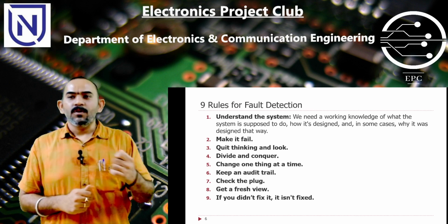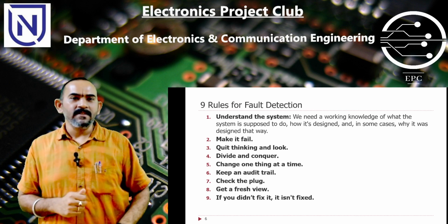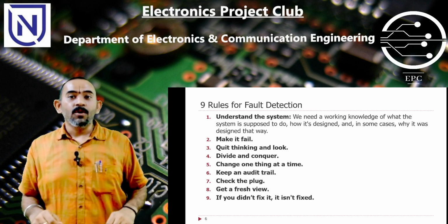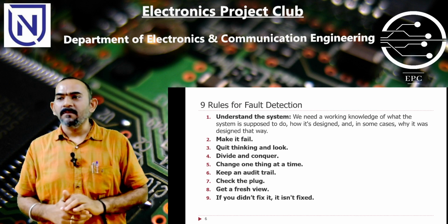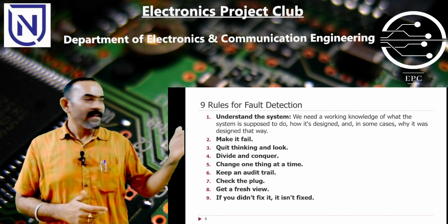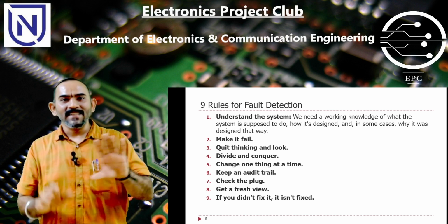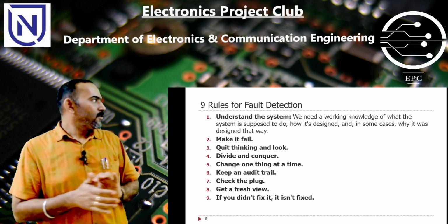Okay, so one common mistake, which happens even in our normal lab: we connect the circuit, don't turn on the supply, and we are checking the output. Output is not coming, we do everything, then check the supply. That is why the name, check the plug. First thing, the most obvious ones, you check that. Okay, so this is what we need to do.